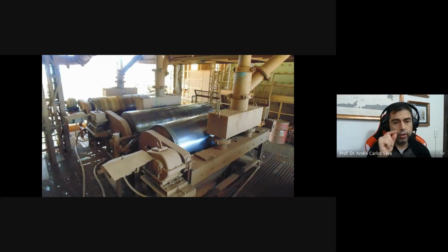That's the first one, low intensity magnetic separator, and we installed this machine together with the mill. So the material goes to the mill once. After the material exits the mill, it goes straight to the magnetic separation, and then we can remove magnetite and a big part of the magnetic particles. So we're talking about iron particles, not ore. And in the end, we're going to do another magnetic separation, but now with our final concentrate, and I'll come back to that in a few slides.